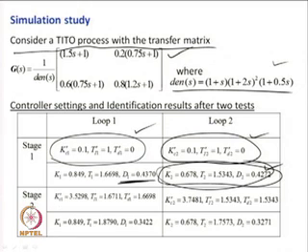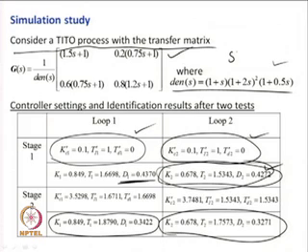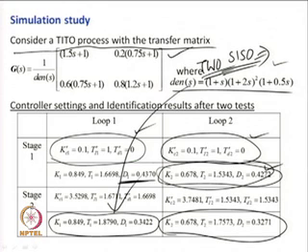Then you get the final parameters for the two SISO transfer function models: k1 equal to 0.849, T1 equal to 1.879, d1 equal to 0.3422, and k2 equal to 0.678, T2 equal to 1.7573, and d2 equal to 0.3271. Thus, we obtain two SISO transfer function models with these parameters after two relay tests, and these final values are found to represent the dynamics of the TITO process.